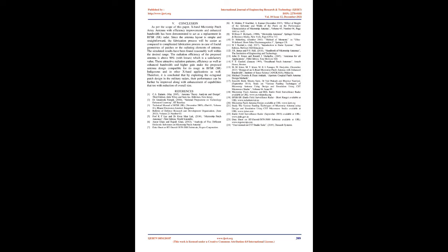The best value of S1,1 obtained is -12.904 dB at 10.2 GHz in the desired X-band, 8 GHz to 12 GHz. The value of gain obtained is 31.08 dB, with losses, which is an improvement of 3.95%, approximately 0.4%, considering losses. The VSWR obtained is optimal, approximately equal to 1.5, at 10.2 GHz. The value at 10.2 GHz is the desired value with good matching and minimum losses.